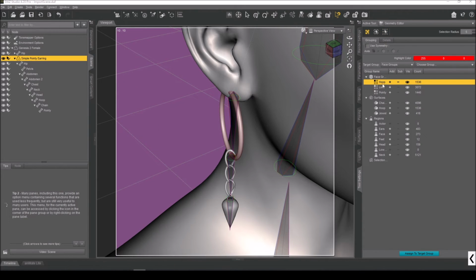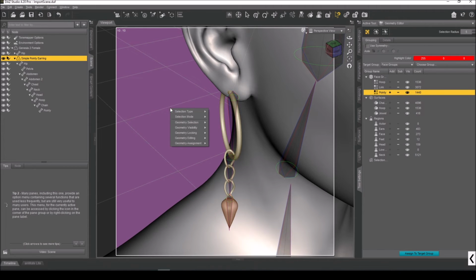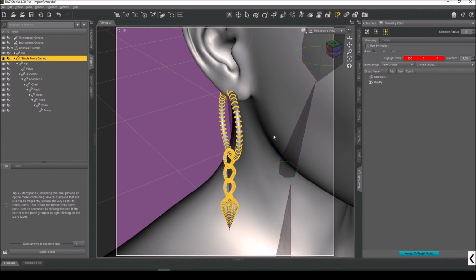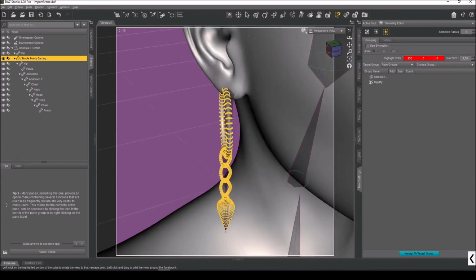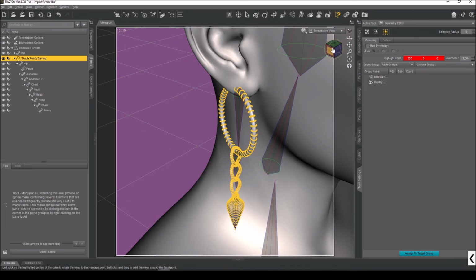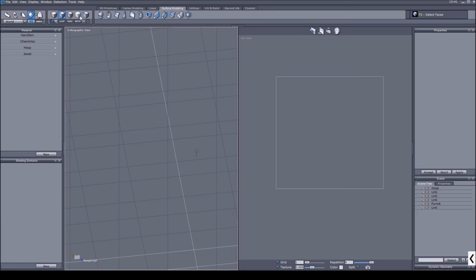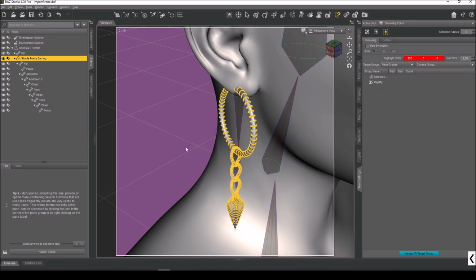Okay, a step back. We're not just going to click on these, we're going to click on all the pluses. So we have all of them marked, and then we're going to geometry selection, convert selection, and to vertex selection. So now you can see that everything is marked. Basically, what we did now is we changed from faces to points, from the manipulation standpoint. From select faces to select points. Basically, it's not completely that, but it's close.